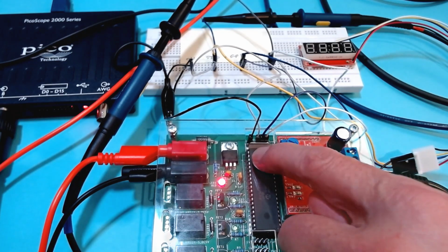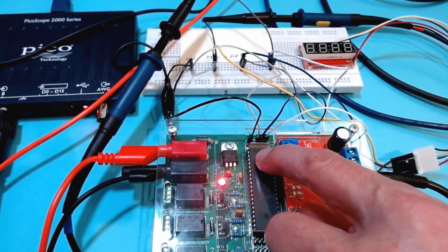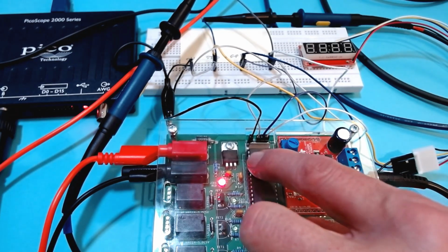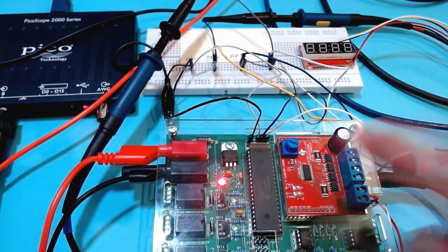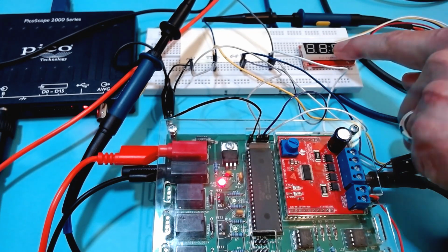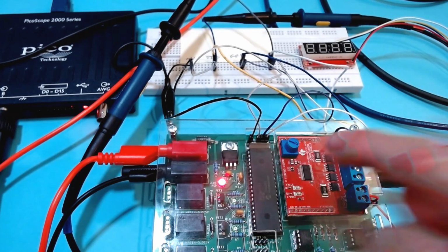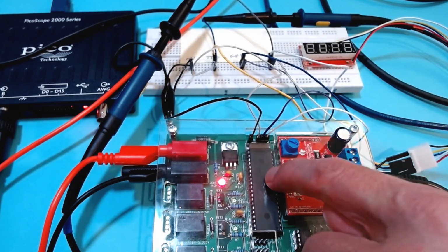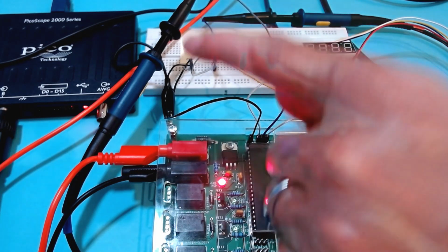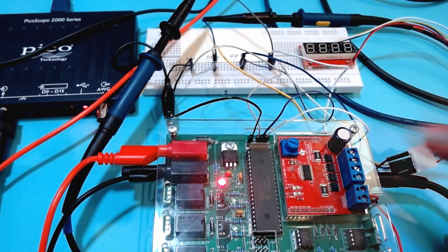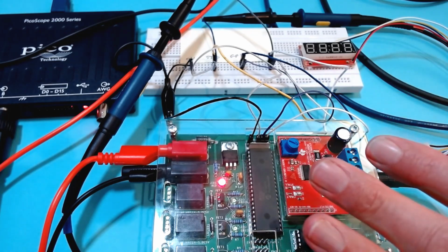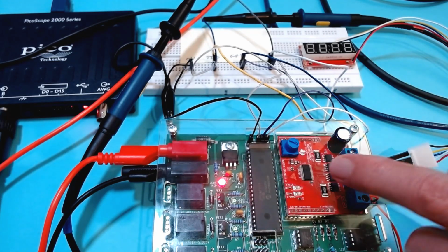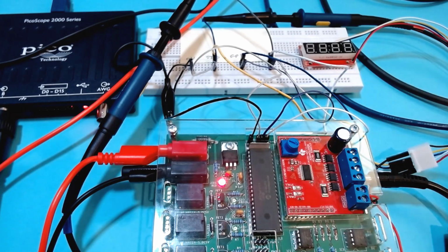Now, this port here is a general purpose output port for I2C or SPI devices. Normally this is the display that we're talking about, and this would normally plug straight into this port. However, in this case, I want to break out the wires so that I can actually look at this and demonstrate to you what happens and how to capture a protocol type signal. Okay, and this is what we're doing in this session.